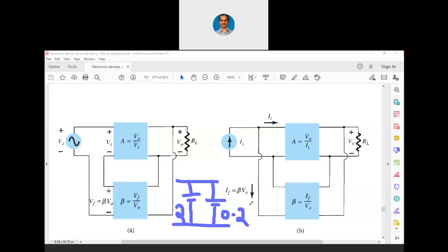That means this particular battery may get damaged by the 2 volts battery. On the other hand, the 2 volts battery may try to charge the 0.2 volts battery and supply a large amount of current to it. In effect, both may get damaged.